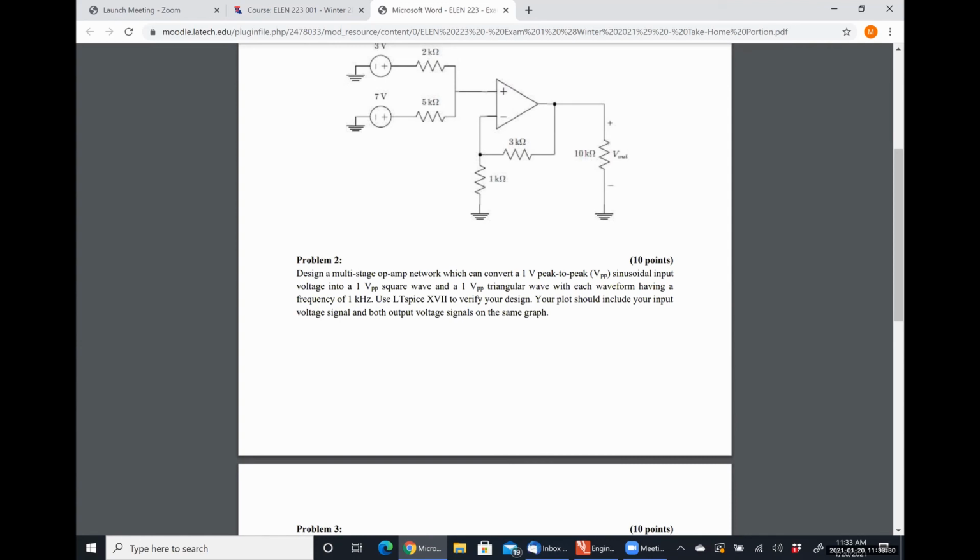So when it goes negative, so when your input signal switches from positive to negative, you're taking the integral of a negative constant, which means you should have a negative slope. So it should be like this, not like this. That's right. It should be like this guy up here. Sorry, that's my fault for misremembering things.